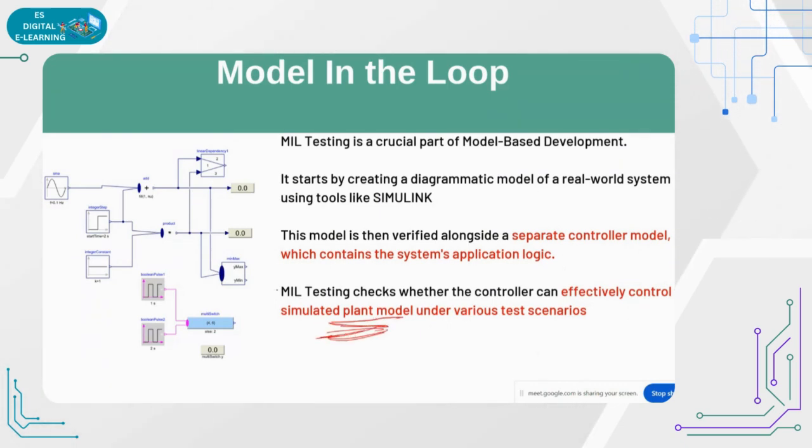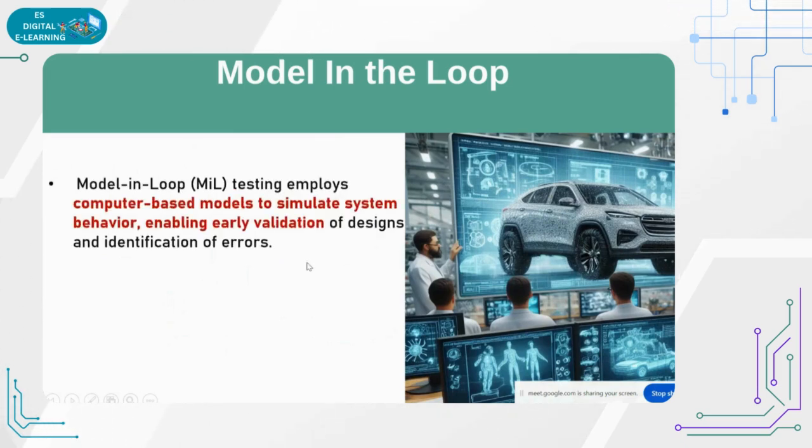You need to remember, the plant model has all the logical algorithms, like addition and multiplication. We are giving the set values in it, and we have the algorithms to make the changes in it, and we have the multi switches. So these are part of a plant model. Whatever input we are giving to the controller, we don't have the physical component, but we are making it in the Simulink plant model.